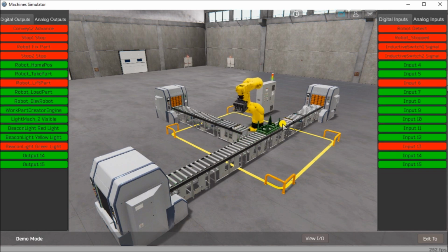So after we've defined the inputs and outputs, and we know exactly what we want with those inputs and outputs, the next step is step 3 of our program development, which is develop a logical sequence of operations for this robot. In order to do so, we can use a sequence chart, and I'll call up a sequence chart that I've created here.